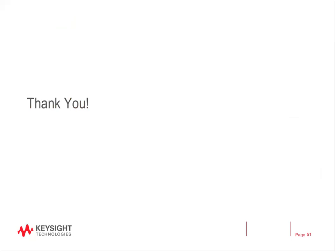Yeah, thanks, Eileen. The point was made that the numbers shown on that slide didn't match up, and that is correct. The example given would have resulted in a noise floor, even if the analyzer was capable of measuring at kTB. The effective noise floor for the input attenuation setting and the resolution bandwidth setting would have been a few dB higher than the spur level that needed to be measured. That was an error on that slide, and it'll be corrected before the final slides go out to you folks.